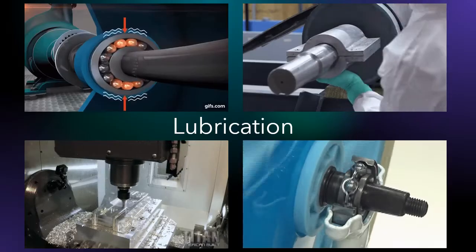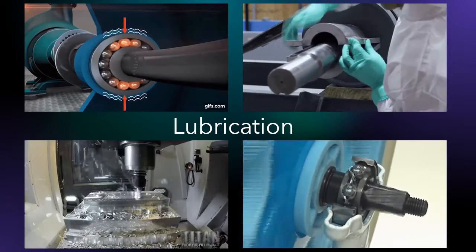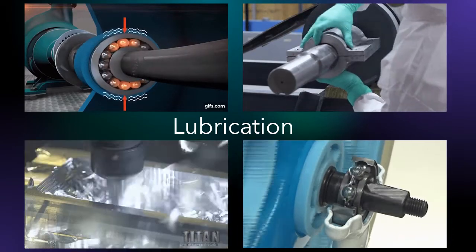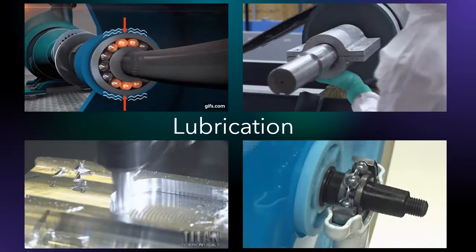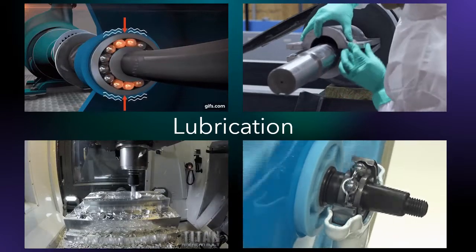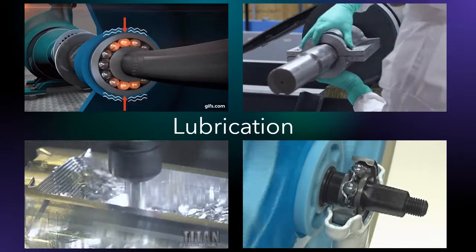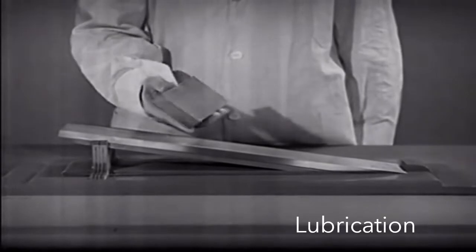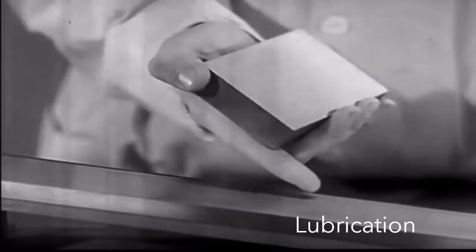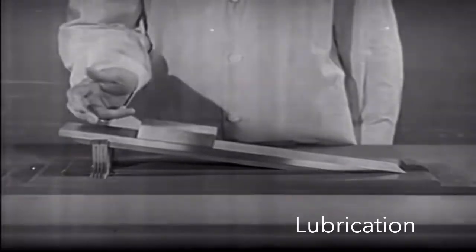Lubrication. In manufacturing processes, as known in various sections, the surfaces of the tools, the dies, and the workpieces are subjected to forces and contact pressures, ranging from very low values to multiples of the yield stresses of the workpiece materials. Also, a relative speed from very low to very high, and finally a temperature which ranges from ambient to a melting temperature. In addition to selecting appropriate materials and controlling the process parameters to reduce the friction and the wear, lubricants, or more generally the metalworking fluids, are applied widely.